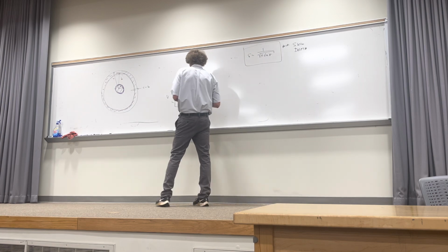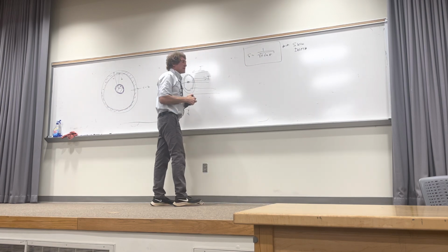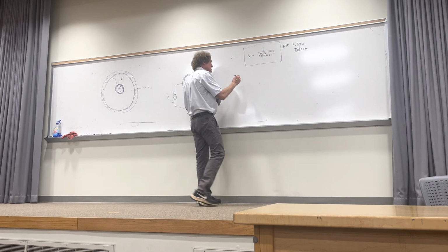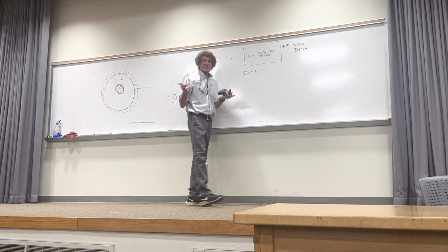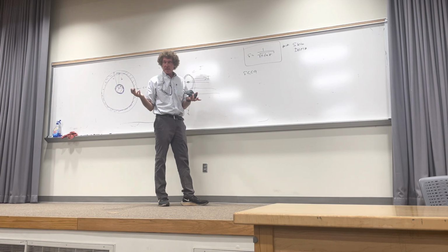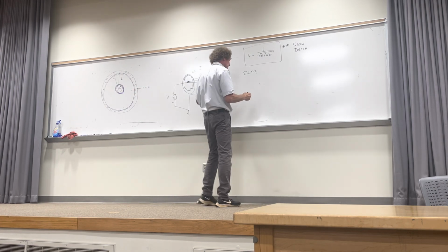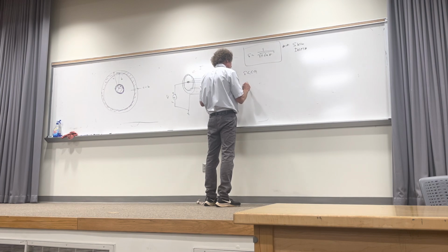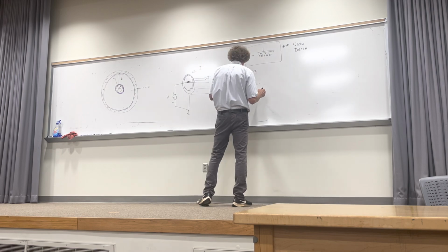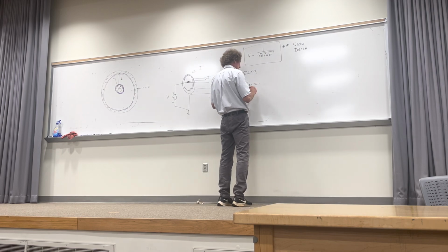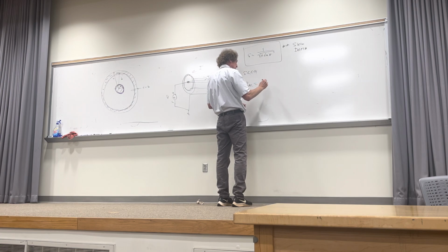That's the one you need to remember. So now you go like this. If the skin depth is much less than a, let's assume it is, and we want the AC resistance per meter of this setup, you would find R_AC would be equal to the resistance per meter of the inner one. That's pretty straightforward. So we're assuming the length is 1 if it's resistance per meter.